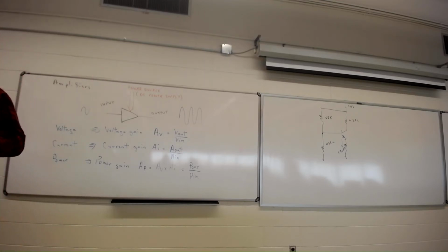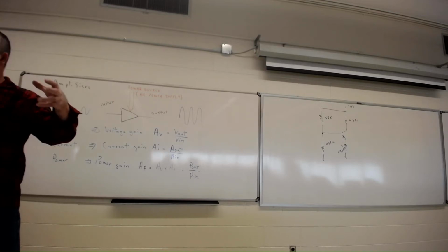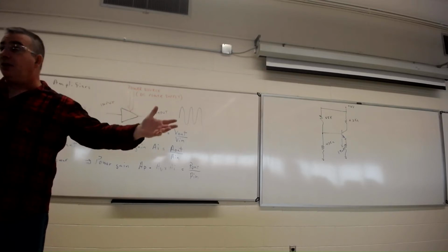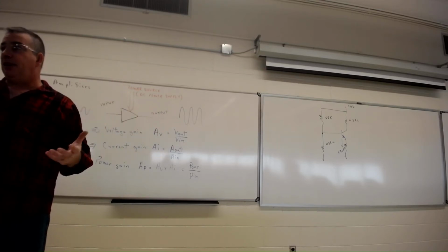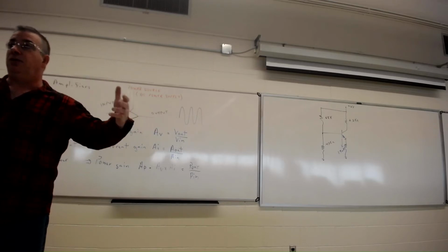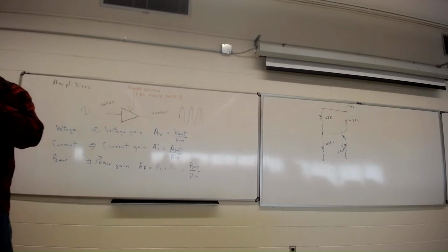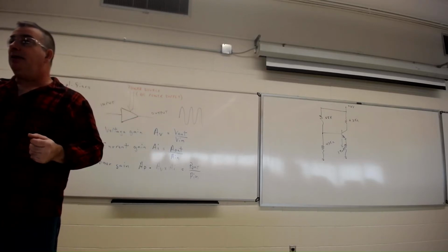For instance, something you might know, like a stereo power amplifier for listening to music. It'll take a very small signal and amplify it. When it gets to the end, if it's driving speakers, you're going to need a current amplifier of some sort to provide the current to a low impedance load. So there's voltage, there's current, together they form a power amplifier.